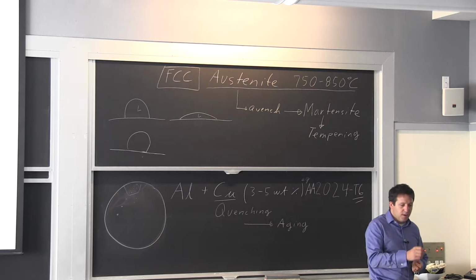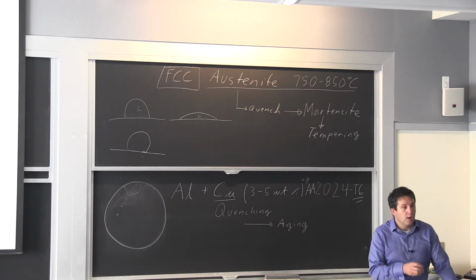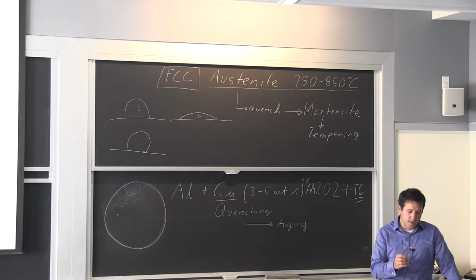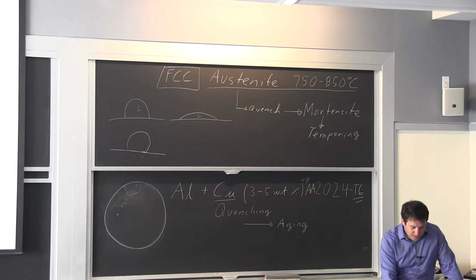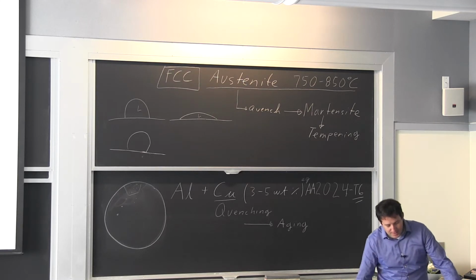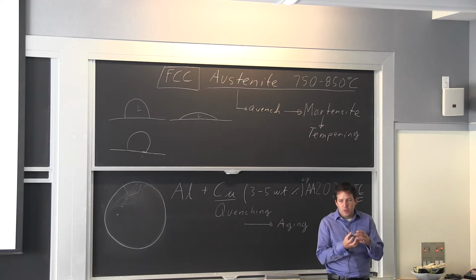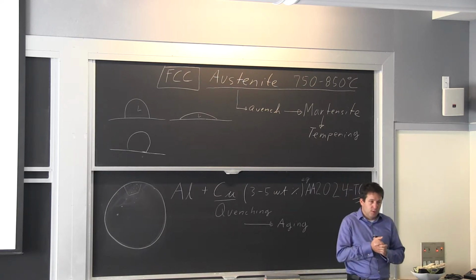But it's very early on that you use all your copper for that transformation, and then it's just a matter of how it's distributed in terms of size. The bigger the size, the fewer of them you're going to have. And they identify them at the very beginning. At this size, the precipitates can be discs. They have very different shapes because they conform with the crystal. They are still part of the crystal. They're not a separate phase. So we call these coherent precipitates.